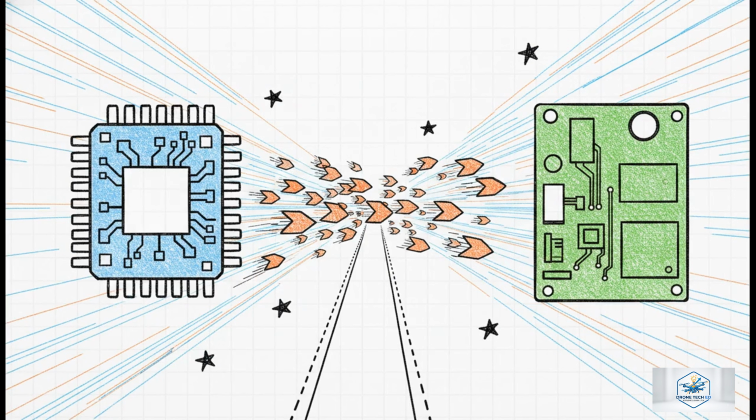But wait, there is a catch here. Sampling your sensors at 8,000 times a second is completely useless if your nervous system has a communication bottleneck. This is exactly why modern drones mandate 32-bit ARM Cortex processors and digital protocols like DShot 600. DShot 600 fires off data packets to the ESC within a tiny 26.7 microsecond window. This guarantees there is virtually zero latency between the brain recognizing a problem and the muscles reacting to fix it.